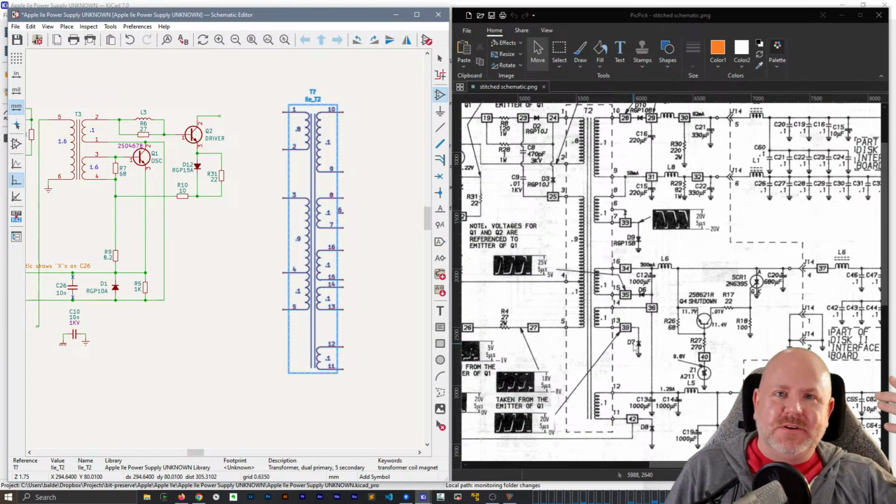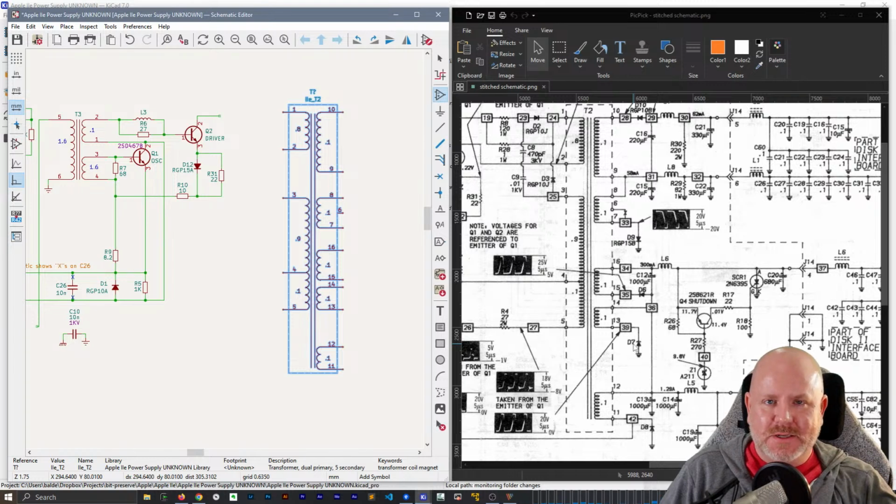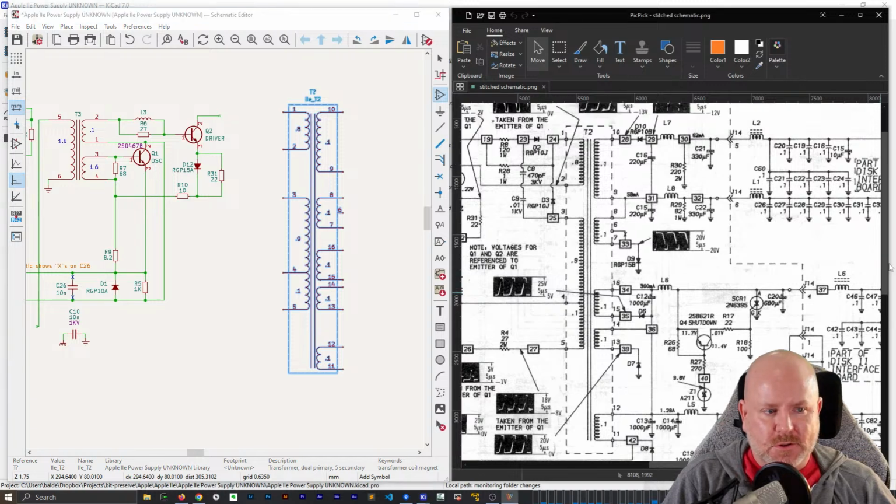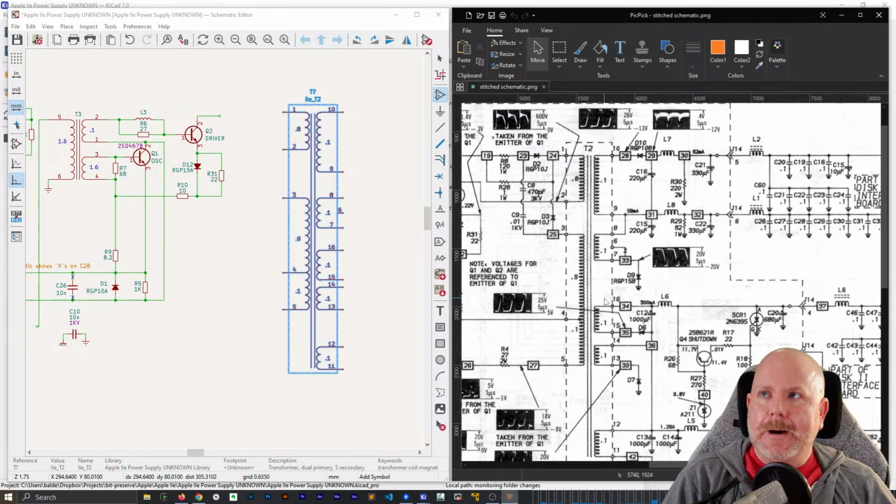So for reference, for those that don't know, I did a review of this box that's a battery emulator, and it comes with some profiles for like AA and AAA batteries. However, the example profiles they provide are wrong. Their internal resistance is at least one order of magnitude too high, which I just don't understand how you do that.